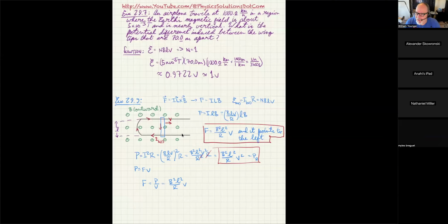And the reason why they bump that voltage up so high is it turns out that from P equals IV, meaning when you actually step up the voltage in what we call a step up transformer, if the voltage goes up by a factor of 10,000, since you're not generating any new energy from this transformer, power that's in must be equal to power that's out. And since P equals IV, if the V goes up, like you do with a step up transformer, the I has to go down. So if you step up the voltage by a factor of 10,000, then you're stepping down the current by a factor of 10,000.